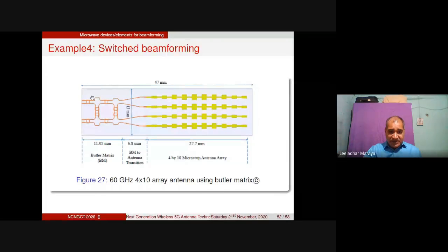Phase shifters are here, and the multiple patches are arranged here in tapered mode, right? Tapered, because they have different areas, different dimensions here. So that's why the taper arrangement is done here. So these all are series fed, but fed with different phases. So that's why four beams can be created in four different directions at the 60 gigahertz, but this is not the aim.